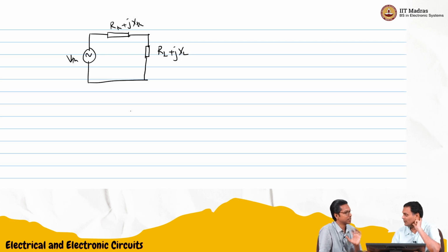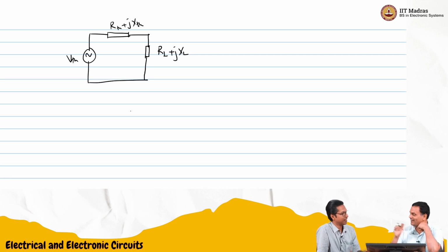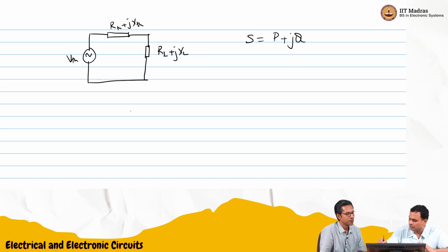Now the same procedure we can follow. What did you want to find out again? Maximum active power transferred to the load. So now that it's complex, you are making it finer, adding more information. So I am looking for active power, not the reactive power, not the Q or the S. P alone. So you're interested in the real part of V I star.